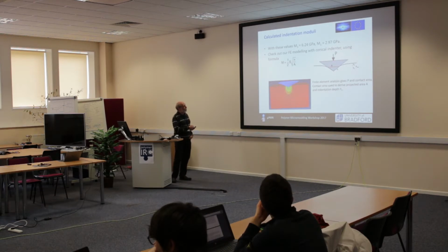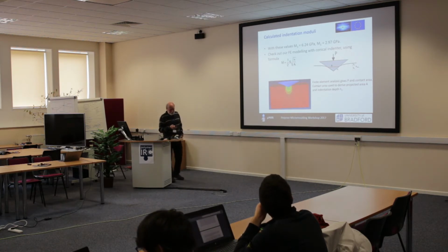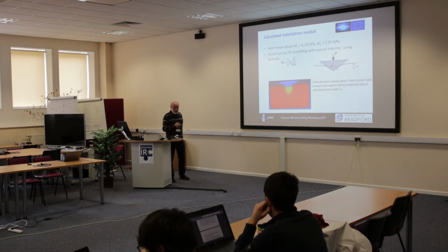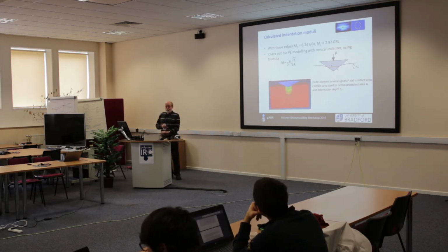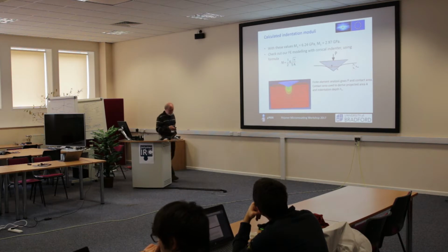What I've done at first in this analysis is look at a conical indenter. So we're simulating it with a conical indenter to check things out, to check that our finite element method is working, our mesh is dense enough, and our procedures for getting the gradient are okay. The differentiation is done numerically, so it's checking out various things to make sure it's all consistent.